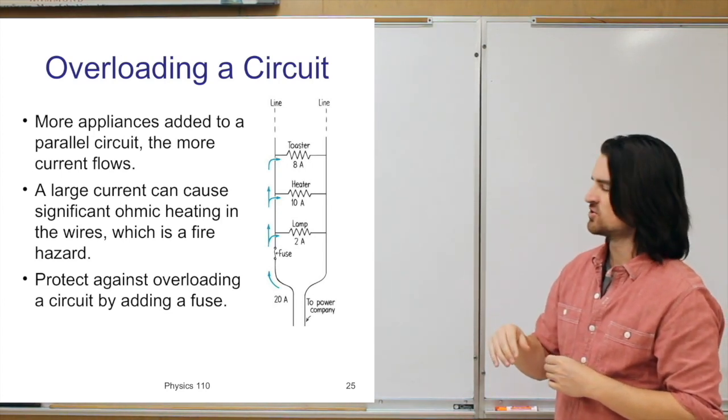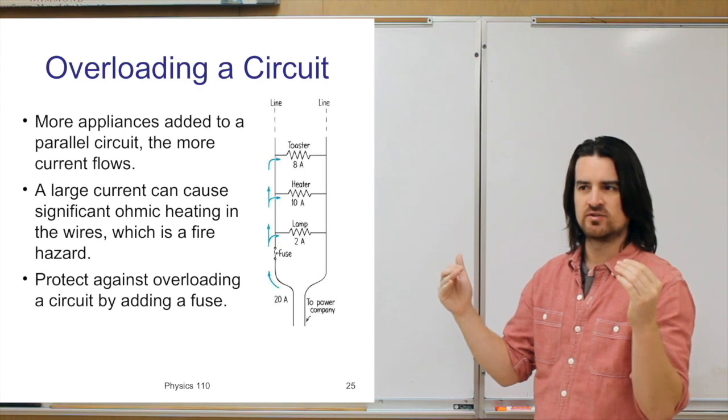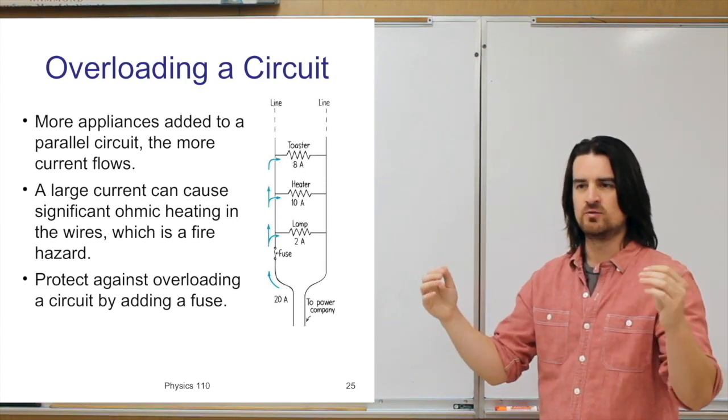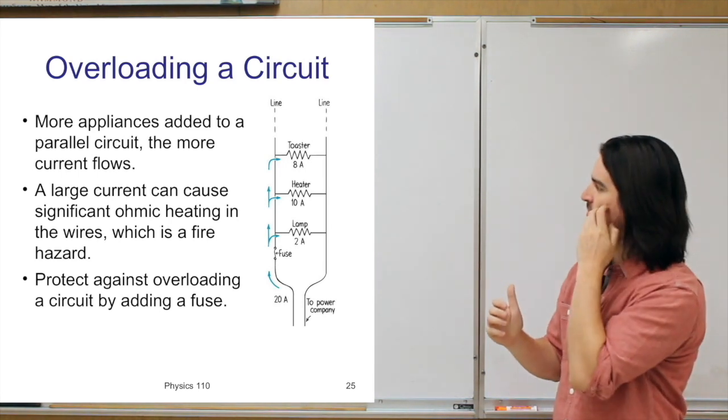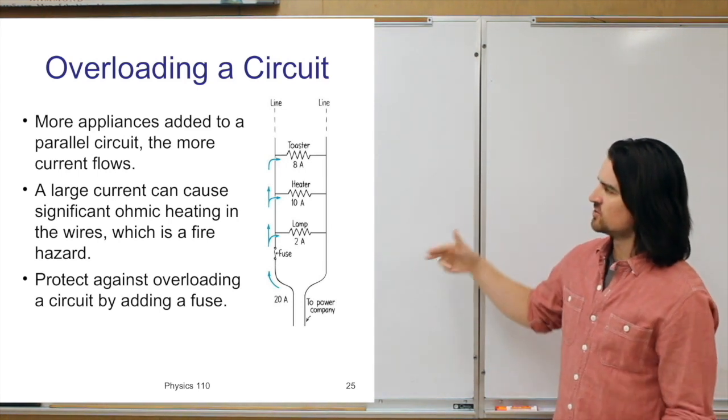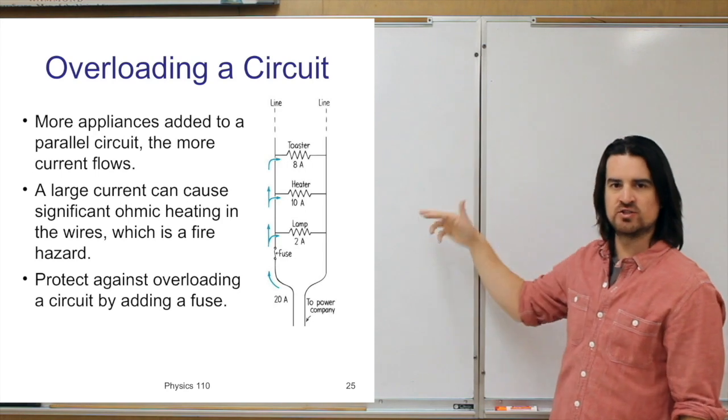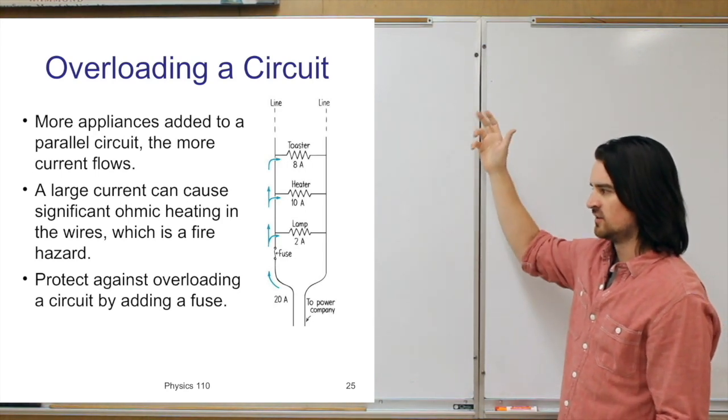And since they're not in series with each other, when you add more and more, you won't get less and less current because you won't have a buildup of resistance in a single path. That allows you to keep connecting more and more components and drawing more and more current, but that can become a hazard